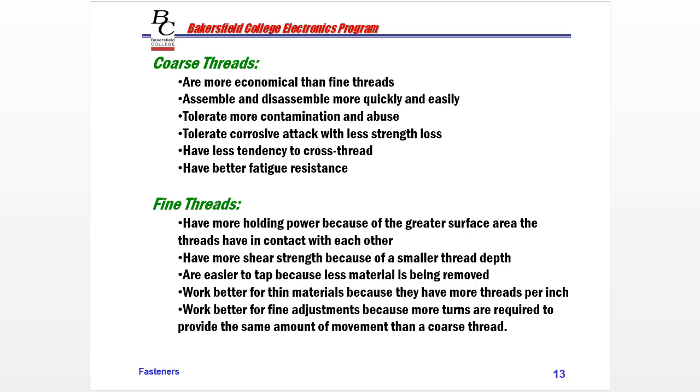They tolerate corrosive attack with less strength loss because there's more meat, the material of the crests. They have a lower tendency to cross thread because there's fewer threads, so the nut goes on more easily. And they have better fatigue resistance. But let's look now at fine threads.